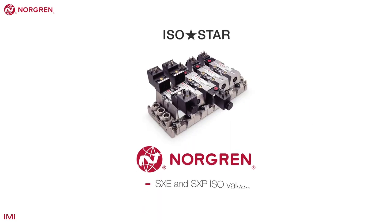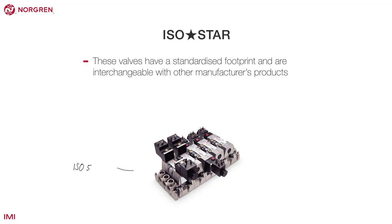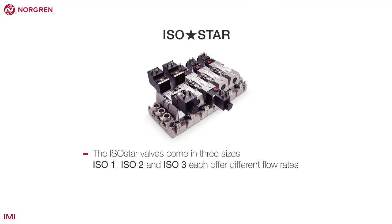ISOstar are Norgren's range of SXE and SXP ISO valves. The ISO standard means these valves have a standardized footprint and are interchangeable with other manufacturers' products. It's only the footprint that is standardized though, and the operating parameters of the valve are not covered. The ISOstar valves come in 3 sizes. ISO 1, 2, and 3 each offer different flow rates. Size 4 is available in the UM22000 series.